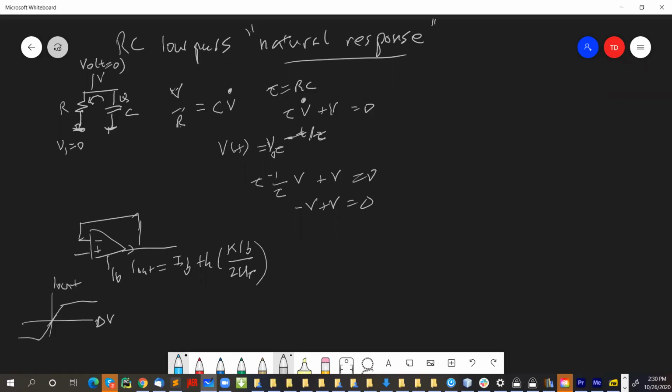Okay, so now what we care about for the equivalent conductance is the slope of this thing. The derivative of tanh of x with respect to x has a slope of 1. So that means that the small signal equivalent GM, or transconductance, is just equal to, let's see, no, this is not correct. Did anybody see that? Kappa delta V. Okay. So that means that the transconductance is, if you differentiate this thing, kappa IB over 2 UT.